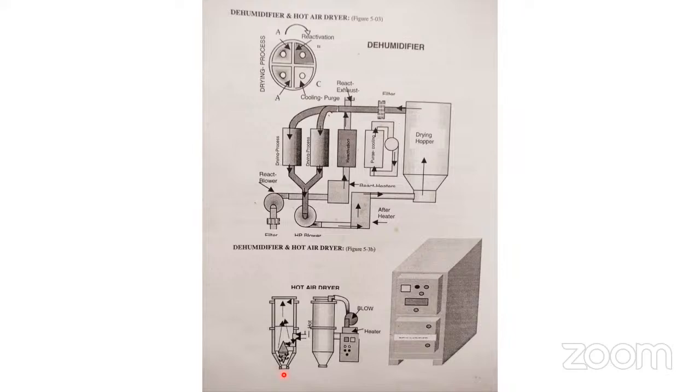Okay, but for polypropylene, we are not heating, sir. Preheater, no, not used. See, generally in areas where the humidity is very high, there you have to use an oven, and even this hot air will work there. Hot air dryer, from here we release hot air. Here is the material. It will go through that. It will remove all moisture. And again, you have to pass this into the hopper of the machine directly. No need to use the dehumidifier for the material.